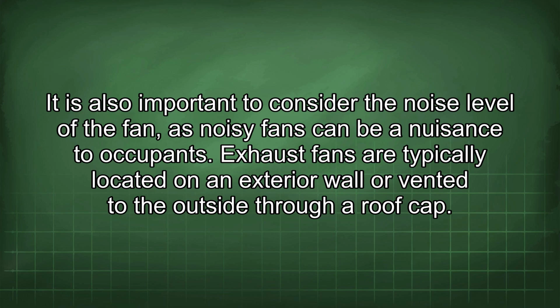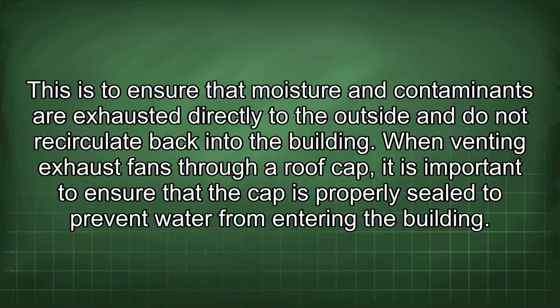occupants. Exhaust fans are typically located on an exterior wall or vented to the outside through a roof cap. This is to ensure that moisture and contaminants are exhausted directly to the outside and do not recirculate back into the building. When venting exhaust fans through a roof cap, it is important to ensure that the cap is properly sealed to prevent water from entering the building.